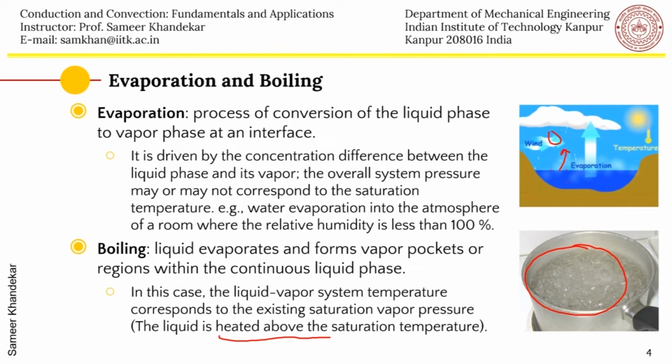So please try to understand the difference between these two processes. In evaporation, the temperature may or may not correspond to the local saturation temperature which it should be, but still phase change takes place. So with these major differences appreciated, we will concentrate on boiling heat transfer in this particular lecture.